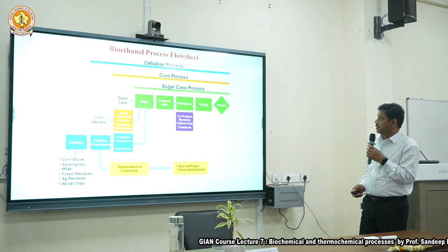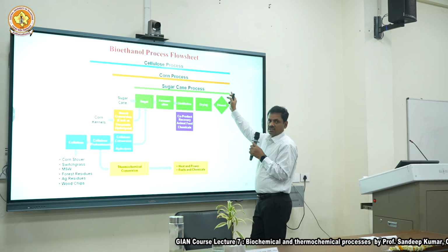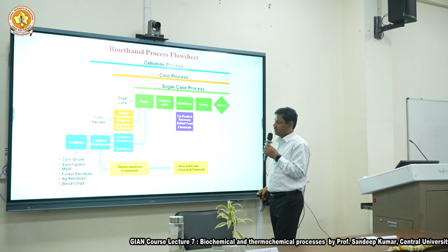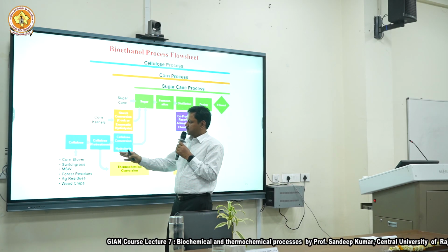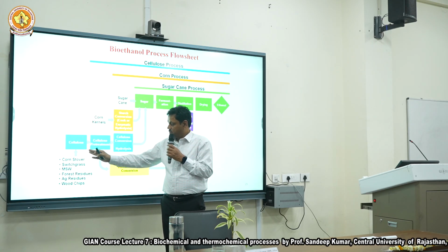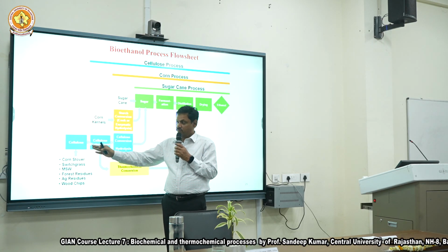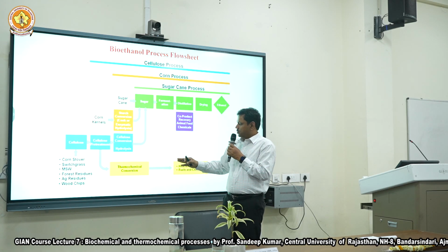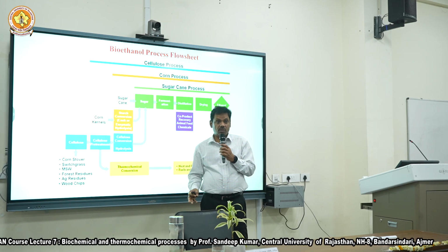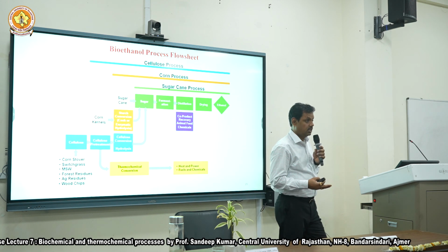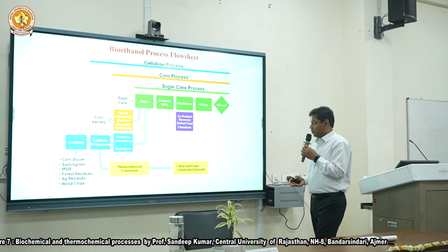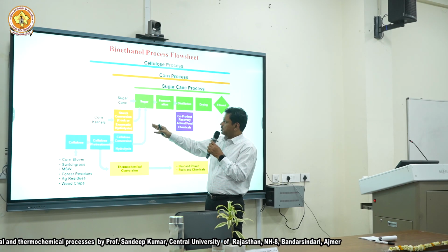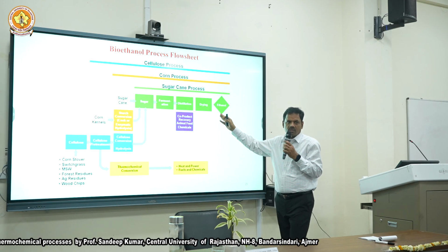Now, if you are adding a cellulosic process, grass, that's why I am showing the wood. What you added here starts from cellulose. You need to reach these things to get cellulose. Okay? So you need to do pre-treatment. Alright? So pre-treatment you can do with a thermochemical process, using alkali or acid or something like that. When you do that, you get cellulose, you do hydrolysis, and then you take the same route.